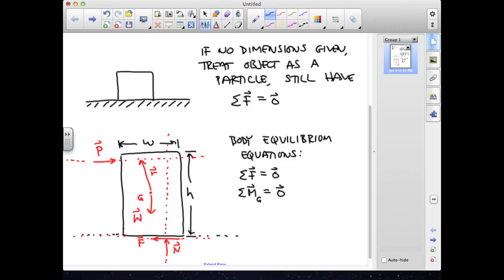The quantity m is called the moment of the force and depends on both the force and its eccentricity, as indicated, for example, by the position vector r from G to pushing force P in the figure. When we write these equations, you should be thinking of force equilibrium as equivalent to translational equilibrium and moment equilibrium as equivalent to rotational equilibrium.